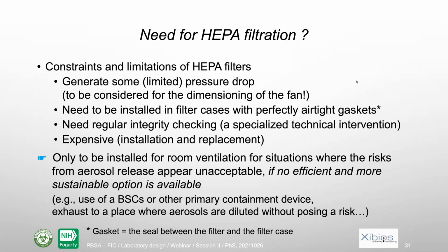Do we need a HEPA filter? Clearly, again, it's not a core requirement. So we only need it if we consider that without a HEPA filter, the risk will not be acceptable. Still, we need to think about such a situation may generate some difficulties. There are some constraints and some limitations with HEPA filters. First, they will generate some pressure drop because the air goes through and it's filtering. The fan that we will need to use, for instance, will need to be more powerful for that.